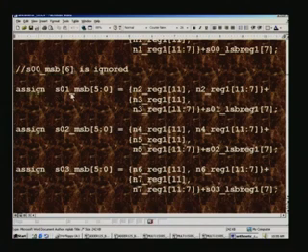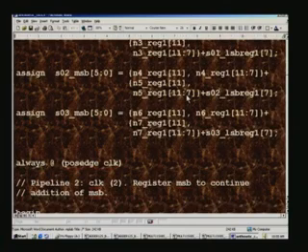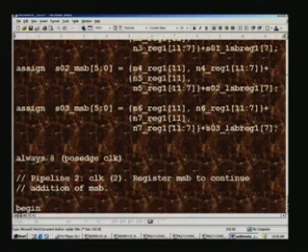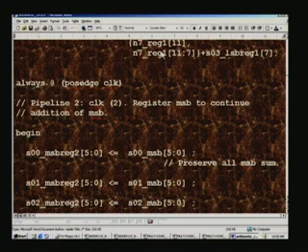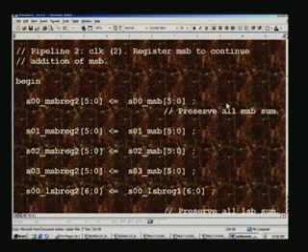So in this case S00, S01 through S03, all of them are assign statements, and this is pre-computed. Because this is a time consuming thing and we want to speed up the system, we pre-compute, and then only with the following clock edge we assign these values to another set of registers. Here we preserve all the MSB sums which we had computed earlier, and in another register we use the same nomenclature, except that this is clock 2, so we add reg 2 to discriminate from this one, and this will be used in the subsequent stages.